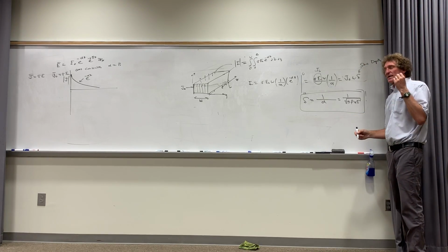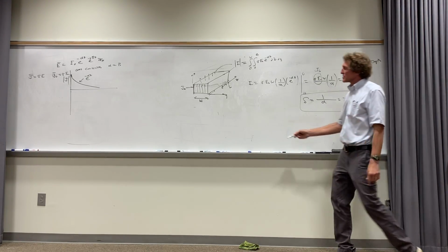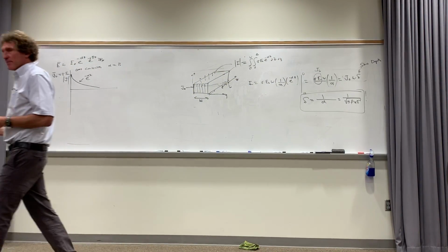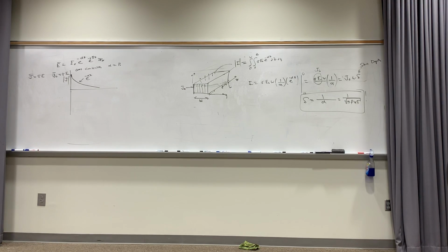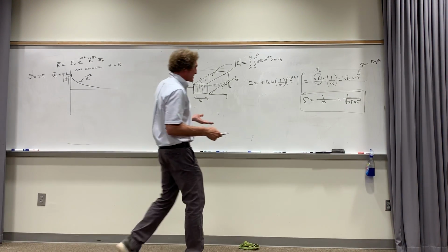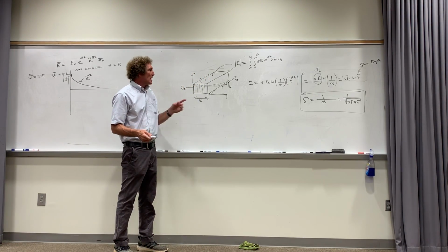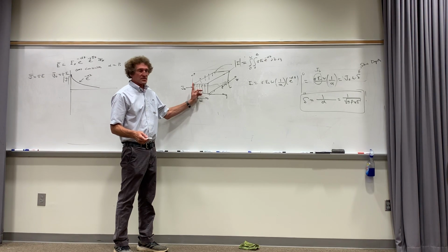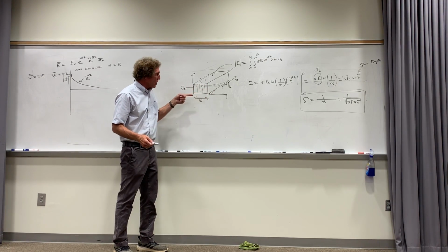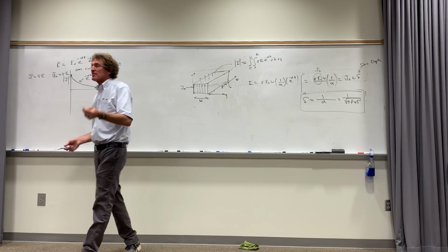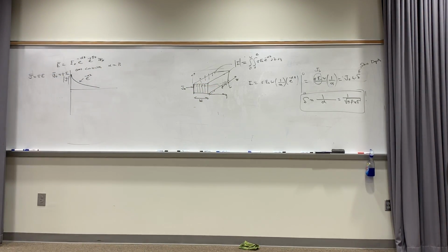And the reason that is so important is that instead of doing this crazy integration all the time, since I know this behavior, if I want the total current flowing in a piece of metal, I can simply say I have the surface current, I multiply by the width and 1 skin depth into the thing. One skin depth down is effectively the distance you have to go to take care of the entire amount of current that's flowing in there.